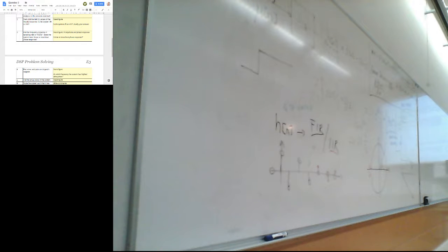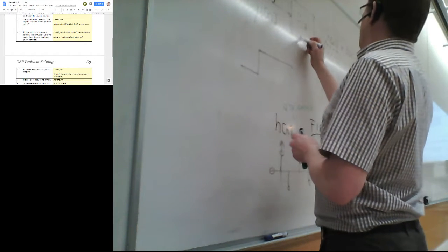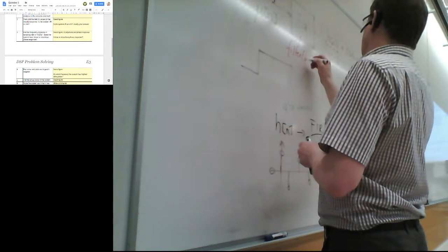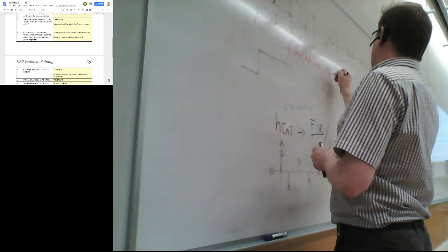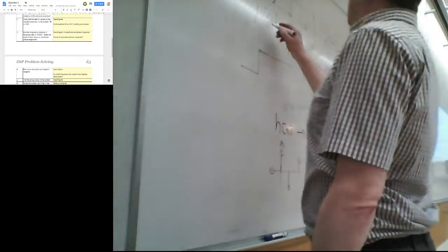So all of that you can get by evaluating the impulse response. In MATLAB, the system implementation is the filter(b, a, delta_in), and that would give you the impulse response.